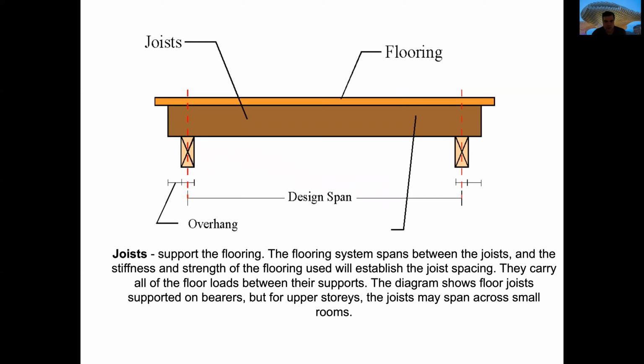As you can see here, next time that you have a building designed out of wood, do not draw in your plans only 2 lines to represent the floor system, because that full floor system will consist of a flooring that, yes, will be 2 lines here in yellow, and after that you will need to have joists that also will be represented with 2 lines.